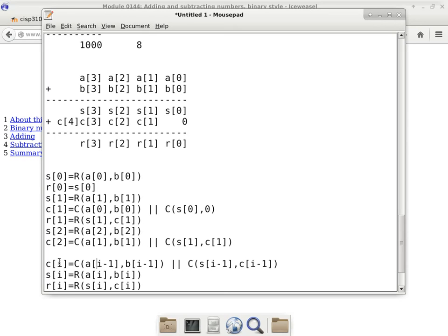They carry. They cannot both be ones though. They cannot. Okay, let's think about it. What you're talking about is, what if this plus this is a carry, and then this one plus this one also makes a carry, right? It cannot happen, because if this plus this is making a carry, it automatically means this has to be a 0. And when one component is a 0, doesn't matter what the other one is, it cannot have a carry. So that's why the disjunction cannot have ones on both sides.